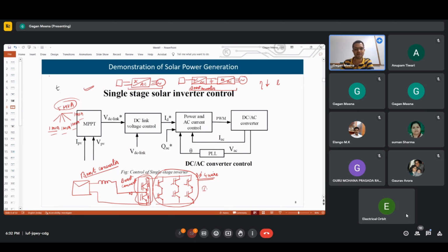Based upon that logic, the DSP has these EPWM pins. Through these pins we get the PWM signals, and we give those signals back to OpenRT, to the driving circuit inside OpenRT. These three signals D1, D2, D3 go to the driving circuit for each battery. From OpenRT we take three currents, three SOCs, and one PD demand.